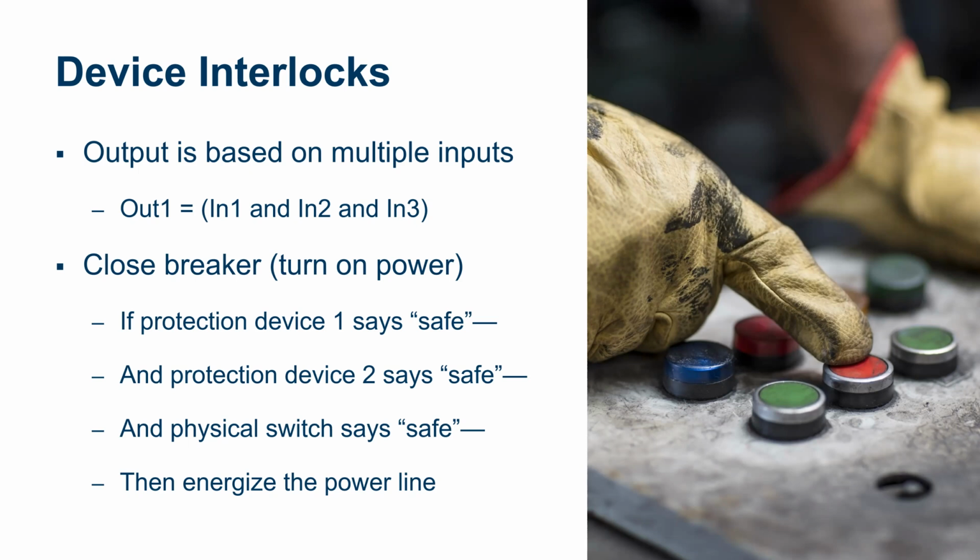This is one of the reasons that I've had to explain to many people in the past why having a close breaker command is not quite as dangerous as it sounds initially. If you're not familiar with these types of protocols, just being able to remotely send the command doesn't mean that I can open or close the thing. Interlocks might prevent this dangerous action. So some kid that hacks into your system and starts sending commands may not actually be able to do anything.